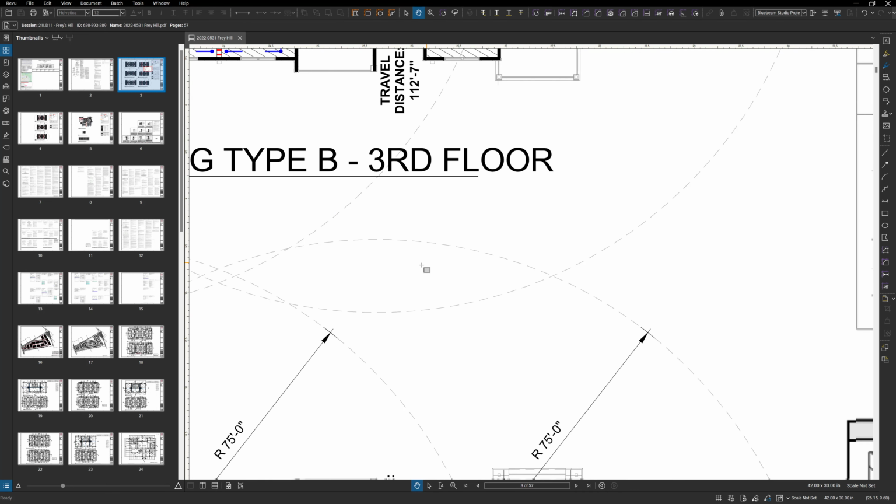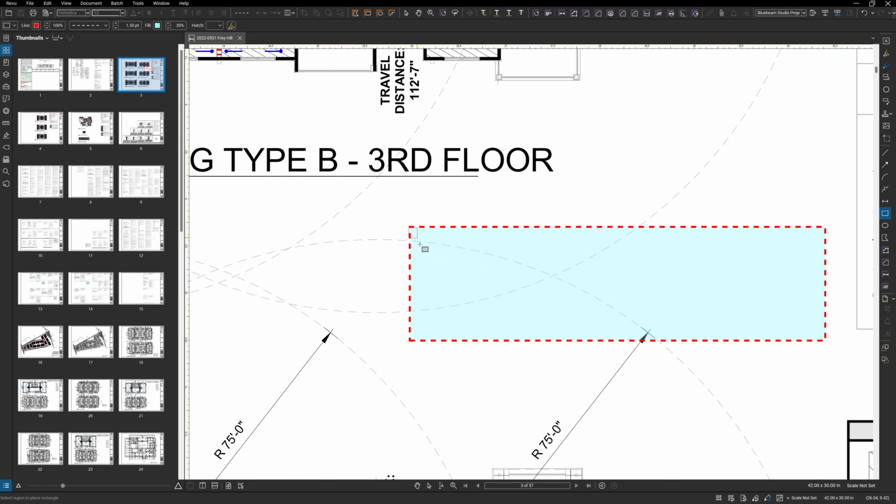And let me be clear here too. Let's say I have a corridor building that has a stair here and a stair here and a hallway down the middle of it. The egress path is from the equidistant point here in the middle. So if this is 100 feet and this is 100 feet, then the egress travel distance would be 100 feet from this point.